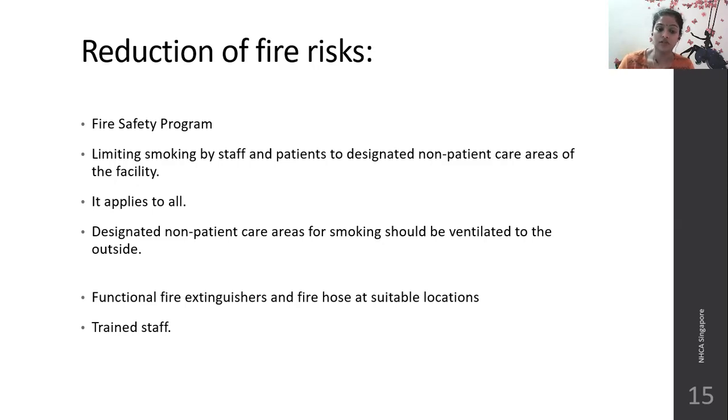Functional fire extinguishers and fire hoses at suitable locations should be provided. And the staff should be trained in case of emergency how to break the glass and use the fire hose and how to shut down the fire. Such training should be given to the staff.